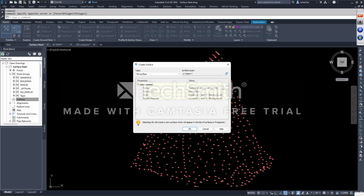Now, a lot of people do not like to have 125 characters in an object name because you cannot read it over here on the tool space, okay? There's a reason for that, not only here under surfaces, but further down, and I'll show you that in a minute. Why you need to keep your names short, but descriptive. Every object in Civil3D must have its own unique name. It cannot have a duplicate name. It'll put a counter after it, like 1, 2, or 3. That's what this counter's for.